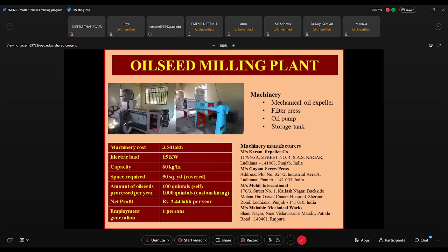Then, if we are to extract some edible oil, already we have discussed the essential oils. Another one is our edible oil, edible oils like mustard oil. What is the difference between edible oils and essential oil? Essential oils basically are not oils. These are basically aldehydes or ketones which give flavor. Whereas edible oils are actually triglycerides having a boiling temperature of more than 200 degrees Celsius.